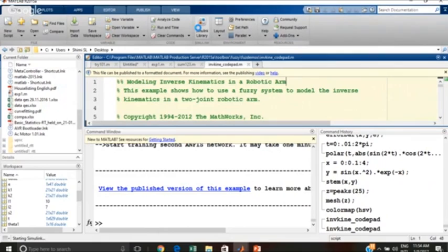Then you will make a controller. The controller will be at a very low voltage level and will just give you control signals. You have a power circuit, in the sense that you will have some thyristors or relays to turn the motor on or off. To control it, you also have some power devices there. When you simulate all these things, it will be a very big mess. When you want to simulate a motor, it should have a field winding, an armature winding, a number of brushes. All together, once you simulate, that itself will come to two pages.